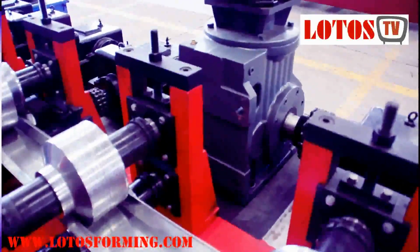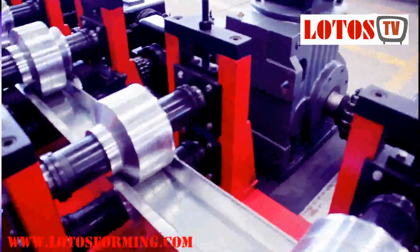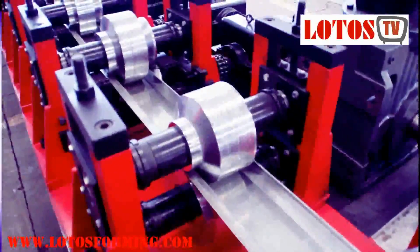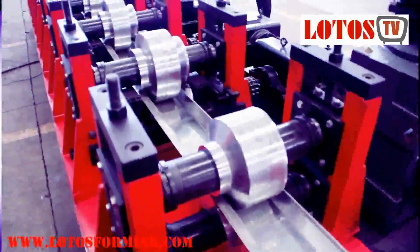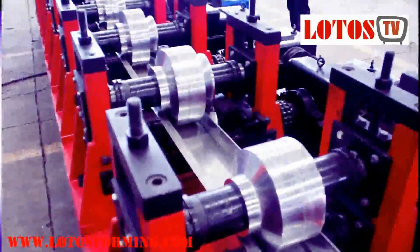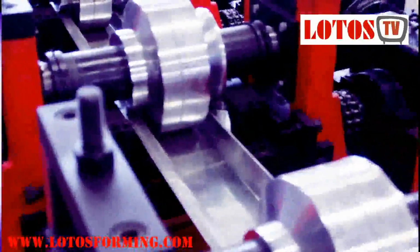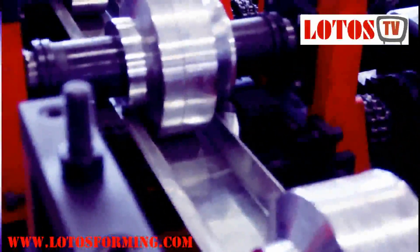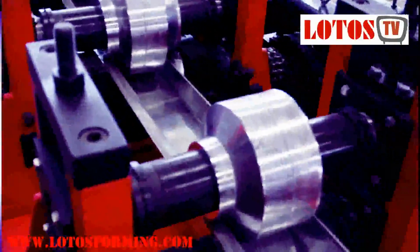We measure the distance between two adjacent dimples in the horizontal direction, vertical direction, and also diagonal direction. We also measure the thickness of the dimple, and compare between the simulation and the actual process. It comes out in very good agreement, with a difference of less than 3%.